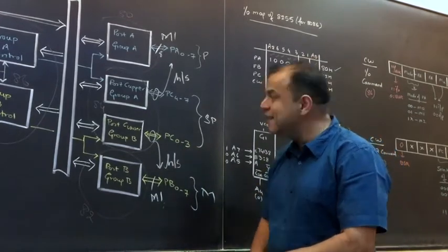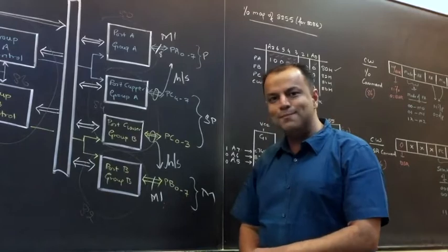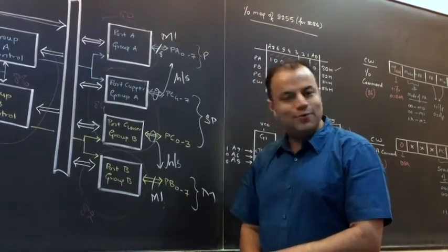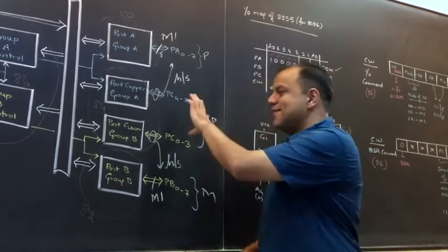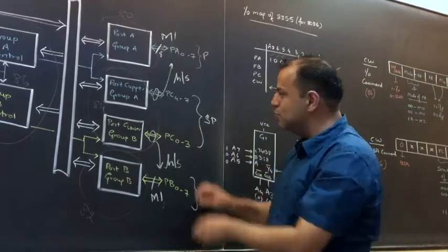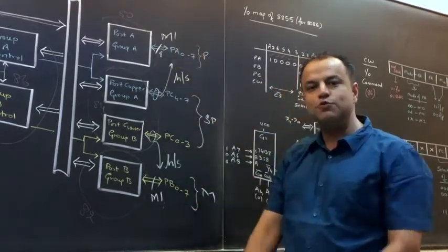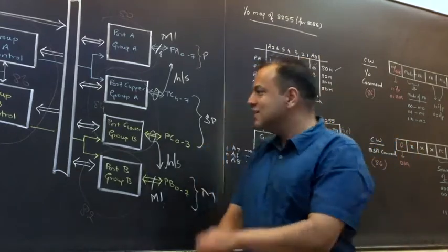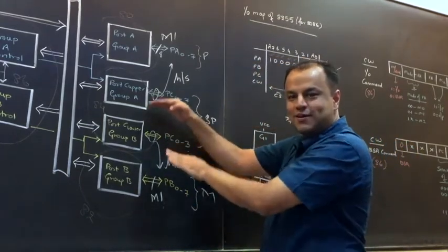Did you understand? If port A and port B both are in mode 0, they don't need any lines for handshaking, then port C is free to transfer data. But if port A and port B go into mode 1, they take away lines of port C to perform handshaking. Are you clear? That's why port C is shown as divided into 2 parts.